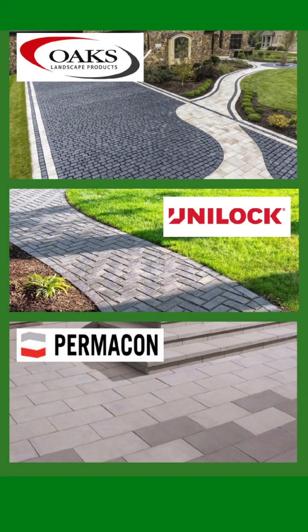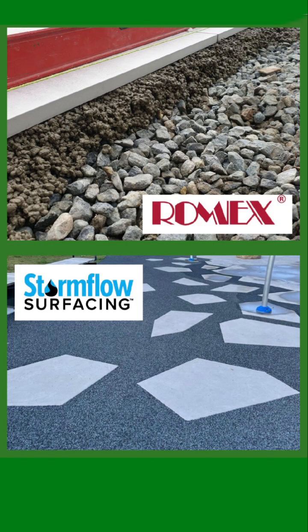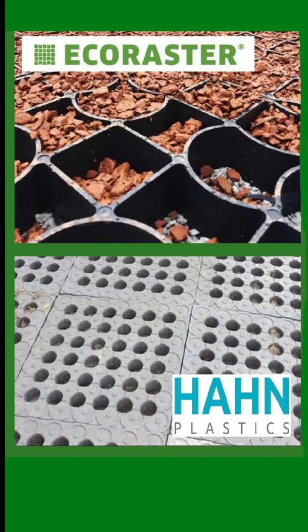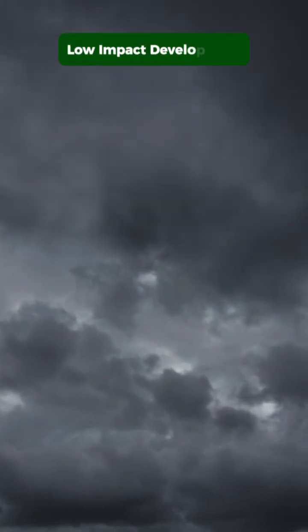Ontario already has many companies producing flood-friendly paving materials. Companies like Oaks Landscape Products, Unilock, and Permacon manufacture permeable concrete pavers designed for Canadian climates. Romax provides permeable hardscape systems along with design support and installer training. Stormflow Surfacing produces environmentally friendly permeable pavement using recycled tires. Meanwhile, EcoRaster and Han Plastics manufacture recycled plastic grid systems that can be filled with gravel or grass to create durable, permeable surfaces.